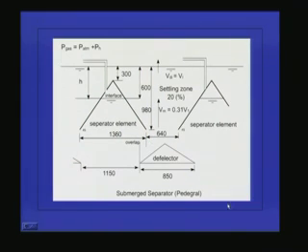And what is happening? The wastewater, solids as well as the gas will be coming here, and here there is a reduction in the cross sectional area, and this separator element is placed at an angle of 45 degree. So, the water will be entering here at a velocity Vm, and this Vm is almost equal to 0.31 of V1, that means upflow velocity, and we can see that the cross sectional area keeps on increasing as we go up. So, here the VDI will be equal to Vi.